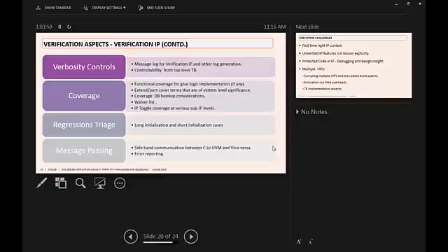And as part of the content, normally most of the test cases we run will be short initialization cases, because of the simulation time. We don't want to run for two or three days. But from a design verification perspective, a long initialization stage is required, because this is what we run in the silicon. We normally don't care about long initialization. So better to have two separate regression batches.